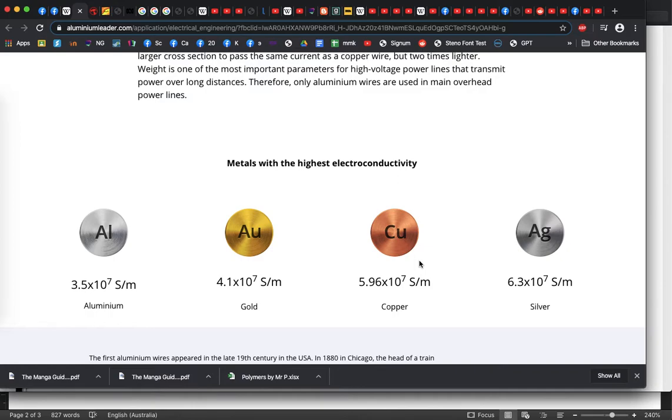Even more expensive than silver is gold, which we generally don't use in electrical conducting very often. In some situations we want copper to be very, very close to pure. ETP, electrolytic tough pitch copper, is pretty close to pure copper. It's more than 99%. In some cases, we want even more pure than that. If the impurities are silver, we don't count those, because silver is better than copper, so it doesn't lose points for having little bits of silver.